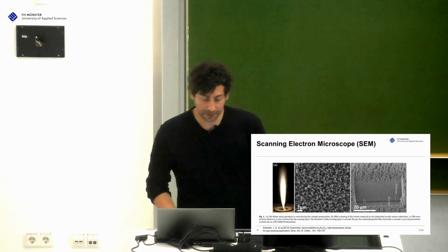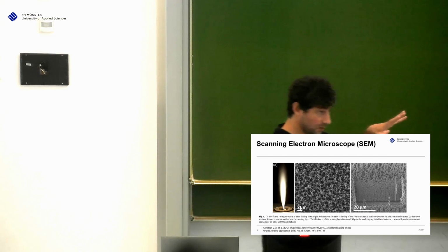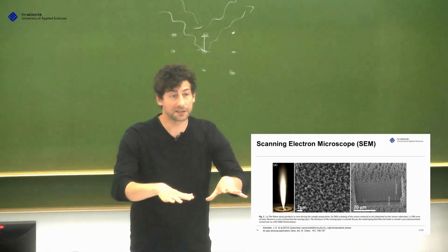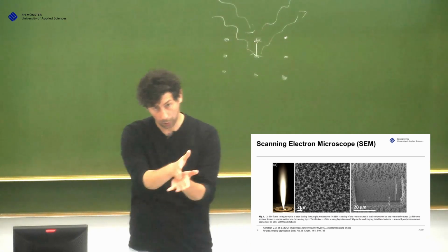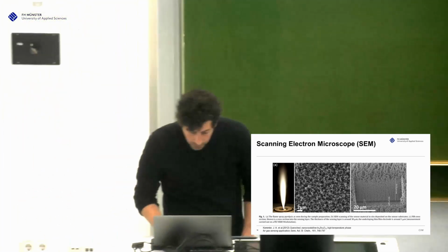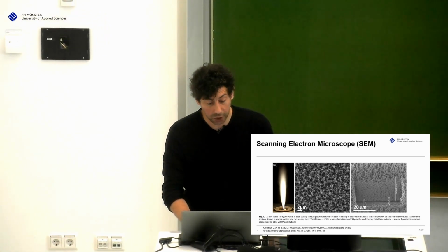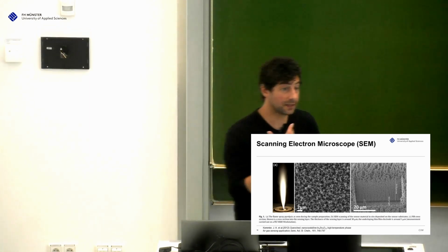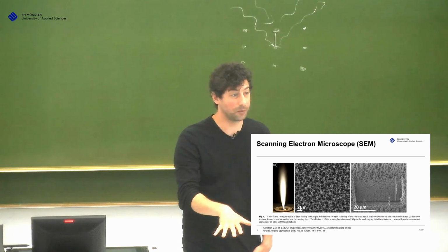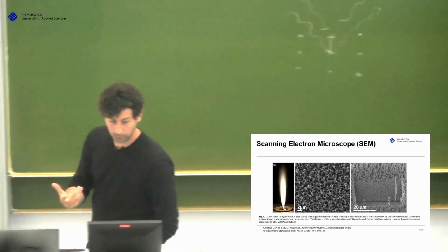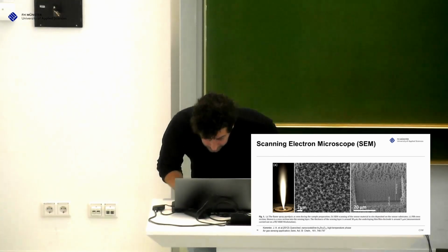And for example, you get an overview. This is an SEM picture of the sensor you make, but also we just look at the top. And the question is, how is the sensor built up, the sensing layer? So we can cut a hole into it, turn it, and then you see, and this is really interesting, that the structure densifies with depth. So the porosity changes with height. This is extremely important information for a sensor, that the porosity is not everywhere the same, but changing. If you don't want that, you have to design your process a little bit differently. And this is what is clearly seen here.